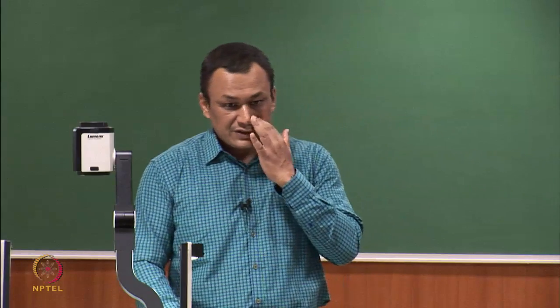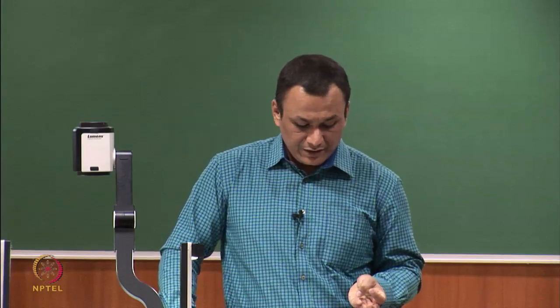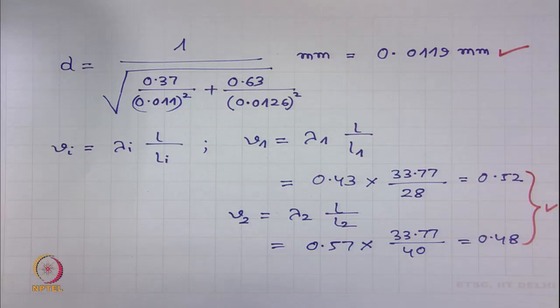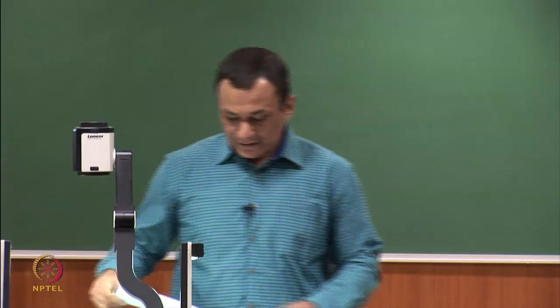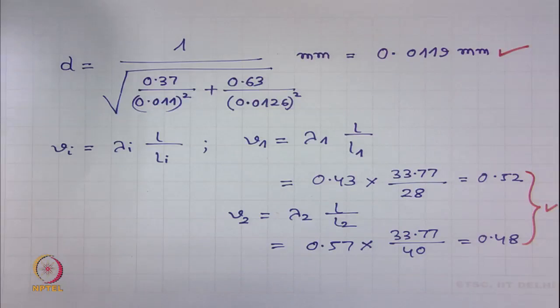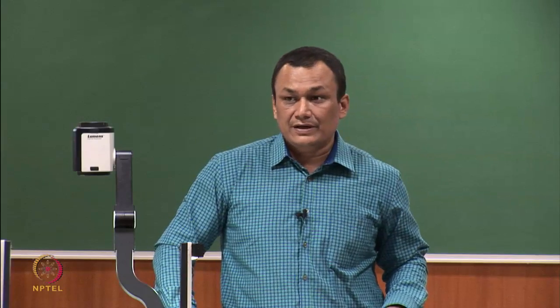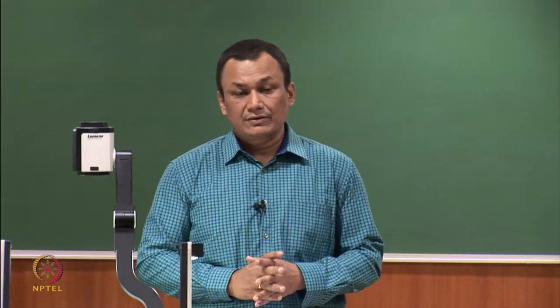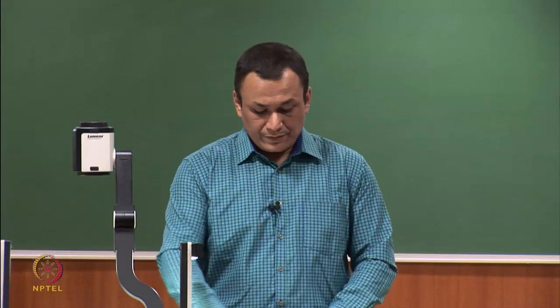So, mass fraction was given, we obtained length fraction, volume fraction and number fraction, and we obtained mean fiber diameter, mean fiber cross sectional area, mean fiber density, mean fiber fineness and mean fiber length, all characteristics we obtained. So, in this way we can characterize a fiber blend comprehensively. So, this completes module 1. Thank you very much for your attention.